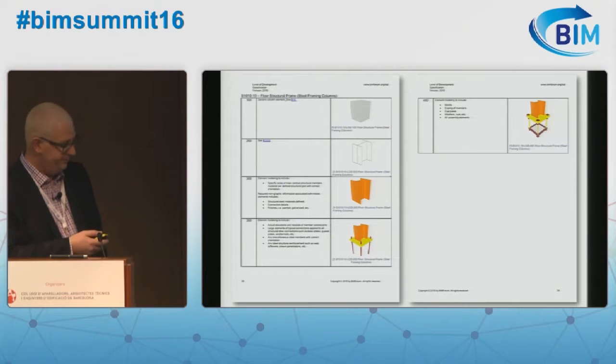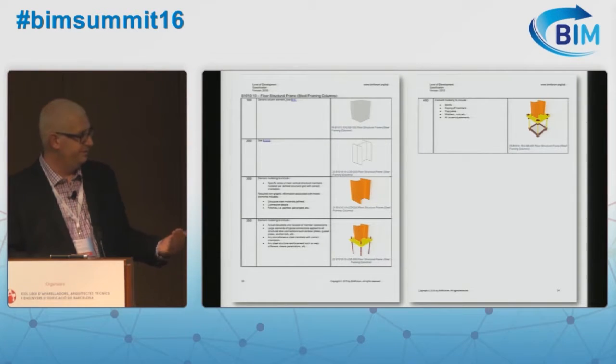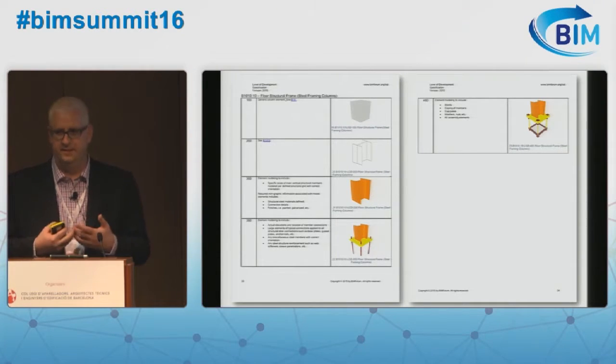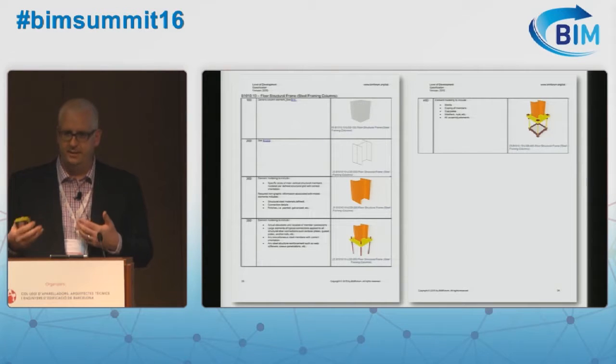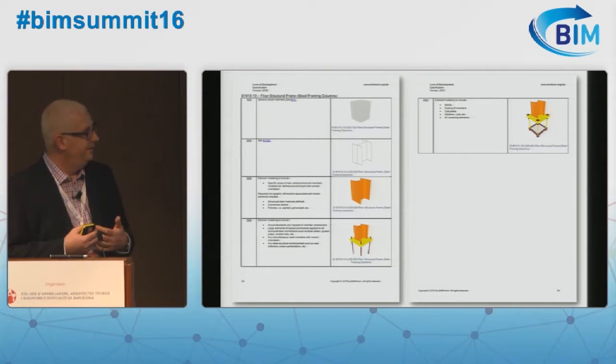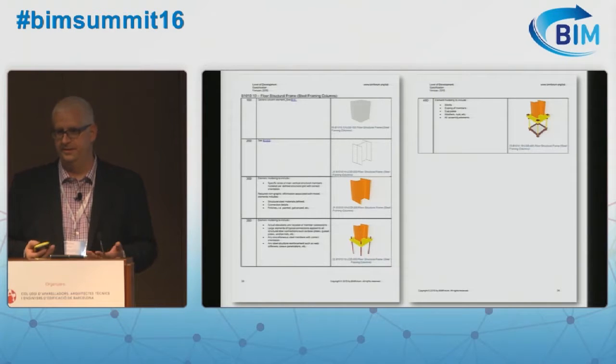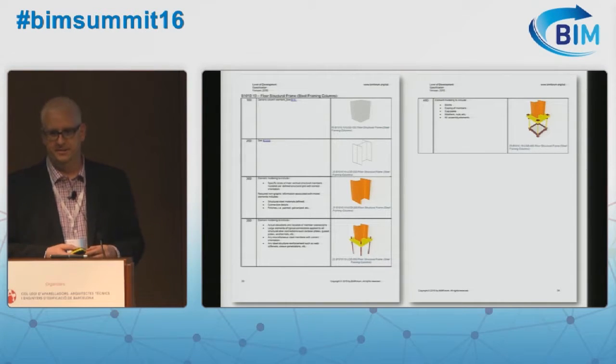And then as I move into 350 in our trade coordination phase, I know that it has to anchor to the building. In the US, the structural engineer wouldn't be detailing this connection location, so the fabricator would start adding that information of things that ultimately take up space. And then at LOD 400, they embark on actually having all the fabrication and installation components modeled in place that are accurate to that specific system that's there.